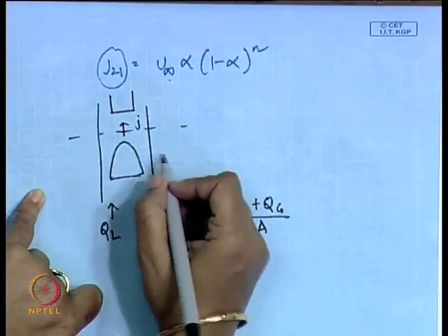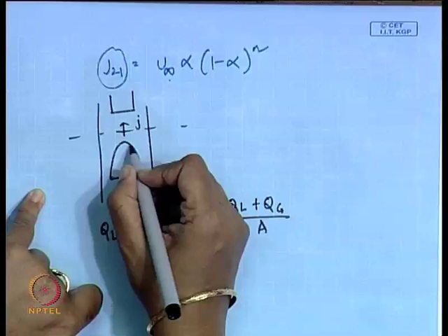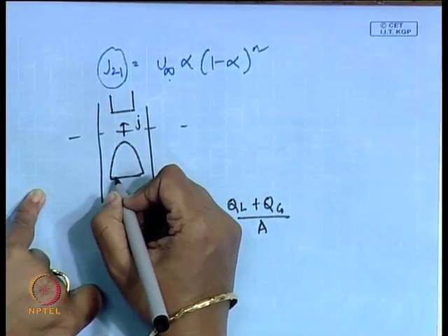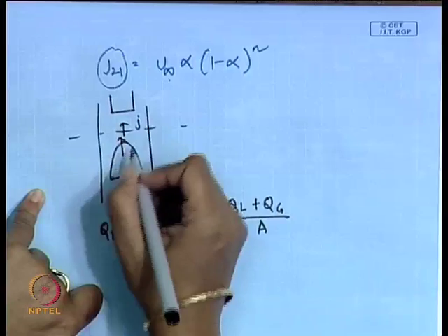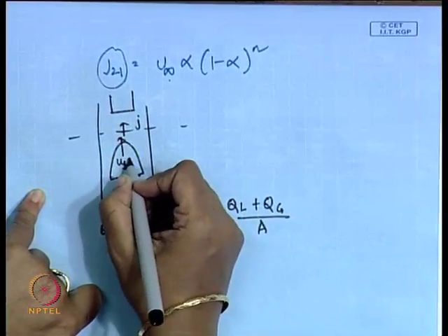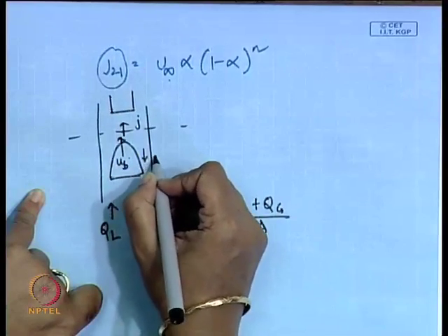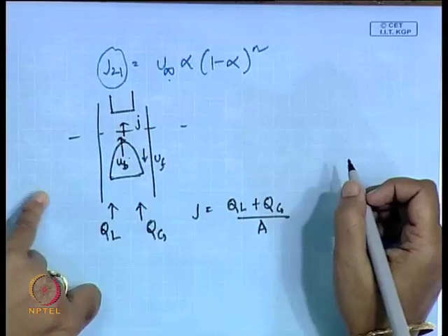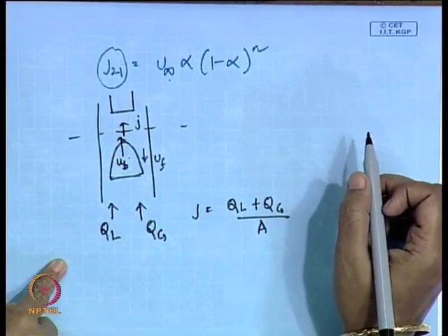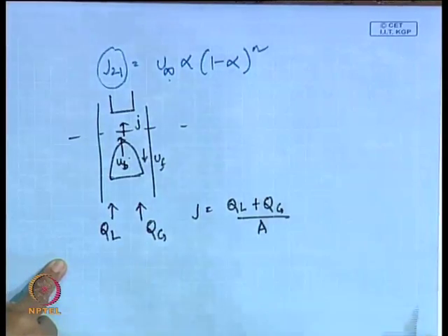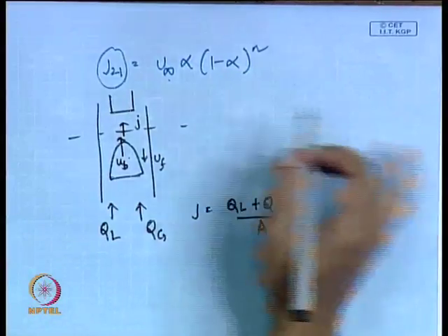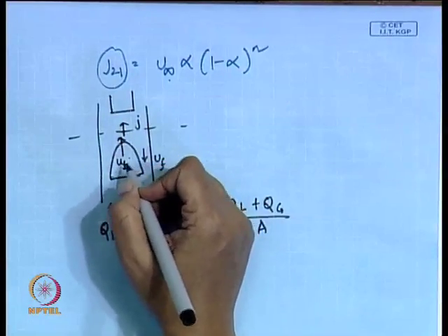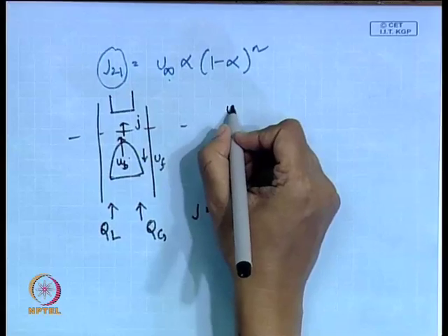Okay. And in this portion, if we assume that the entire gas in the Taylor bubble rises at the same velocity, then this will rise at a velocity u bubble, and the liquid will be flowing downwards at a velocity u f, or the u film. Now, in this case, try to understand one thing. Suppose we consider the drift velocity.